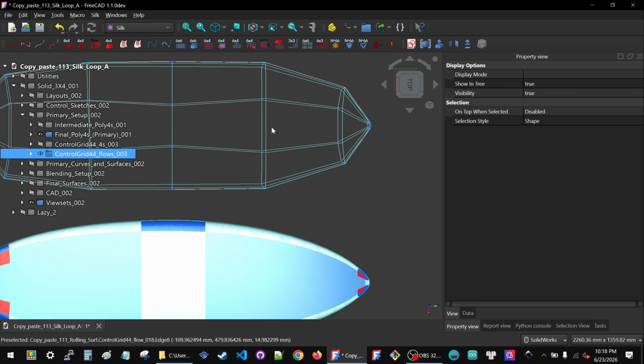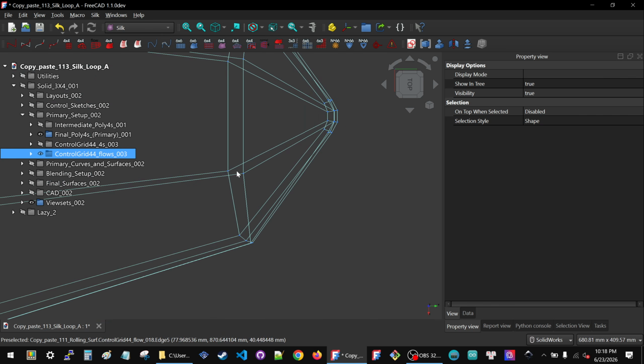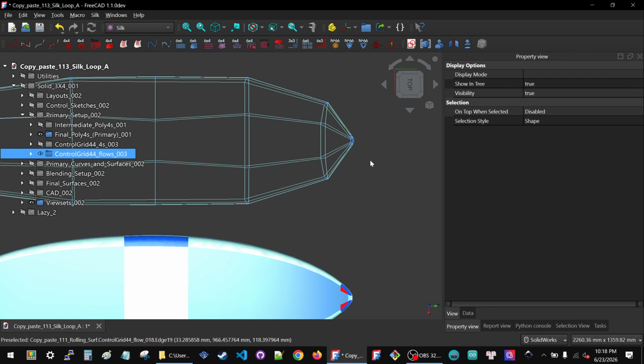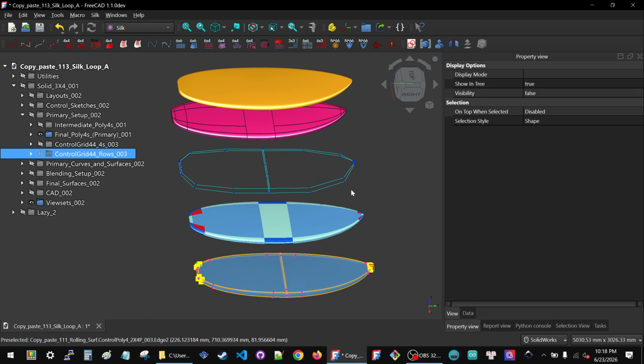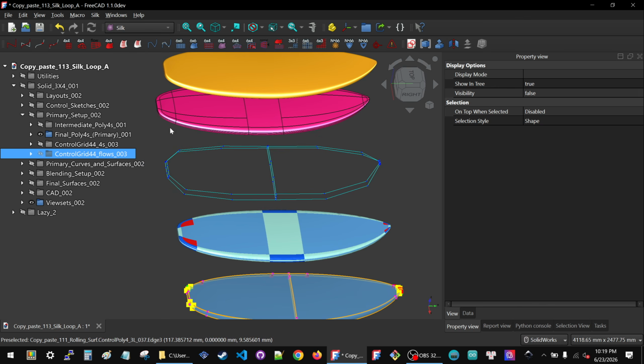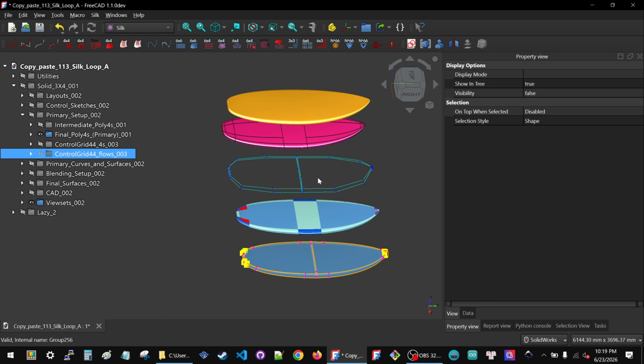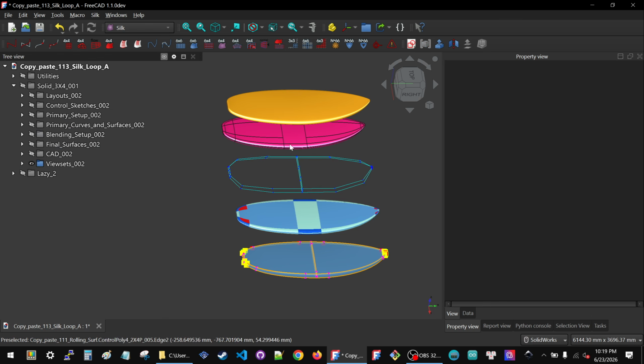I have this section here widening in the middle. You might think, well, it would clearly be better if there was a gradual change in the middle, but what's been prioritized by the flow grids is the flow of these outer sections. You can see that these are reasonable, right? Well, although it's not perfect. Yeah, somewhere in these points here could somehow be somewhere in the middle, but the flow grid is really fighting to deal with this corner here, and that's the result I get, and I think it's passable, although not perfect.